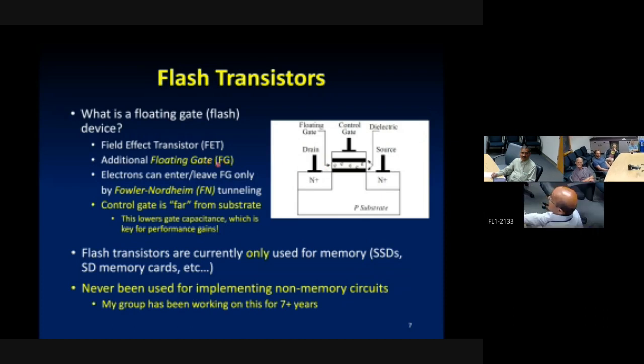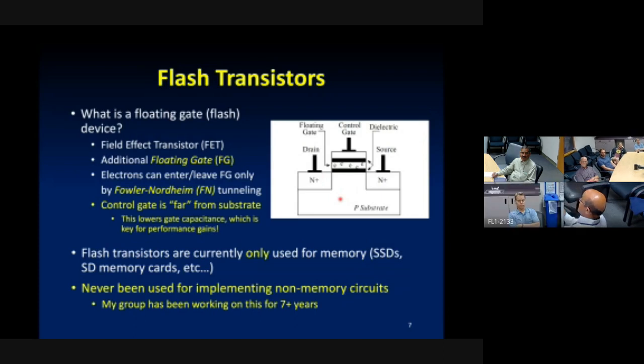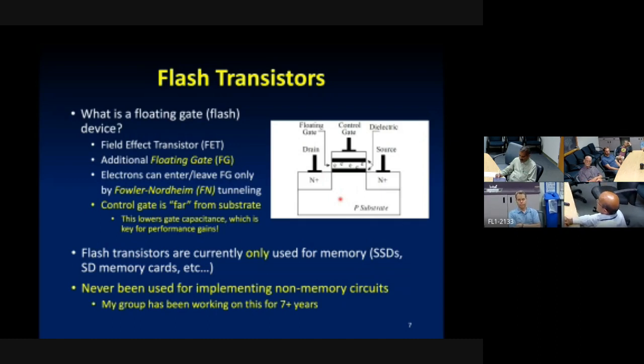So there's this floating gate, and I can inject electrons into this by something called Fowler-Nordheim tunneling. This was invented at Intel, right? And I can also remove them by FN tunneling as well. So I have the ability to inject and remove electrons into this floating gate. And once they're there, they're there. So when they're there, they alter the threshold voltage of the transistor. Remember, we said we wanted to alter the threshold voltage precisely. Well, that's the mechanism. The FN tunneling is what allows me to alter the VT, because the absence or presence of electrons here manifests as a VT change.